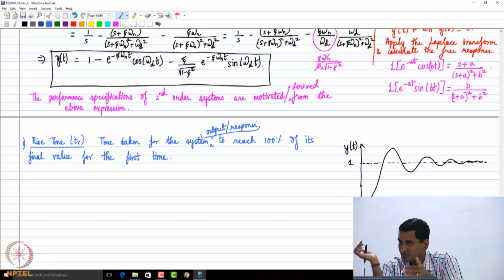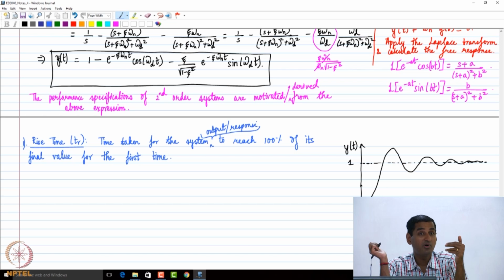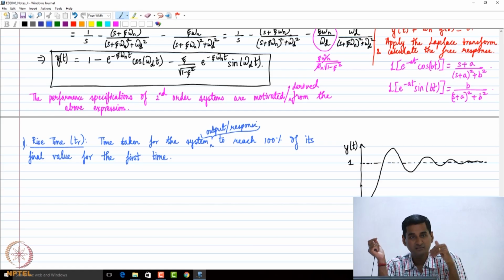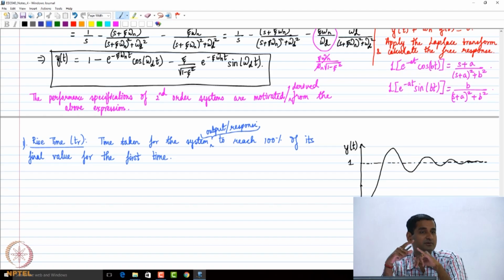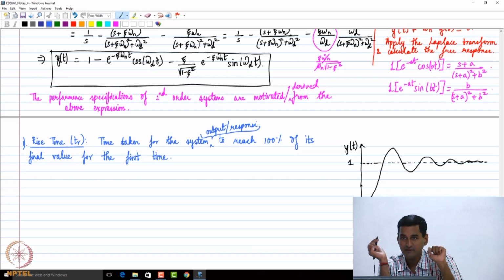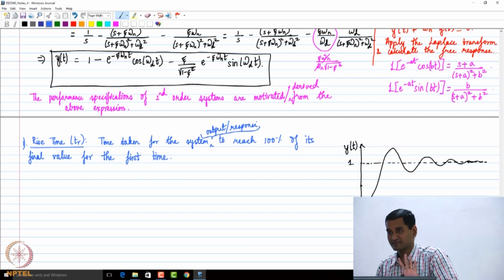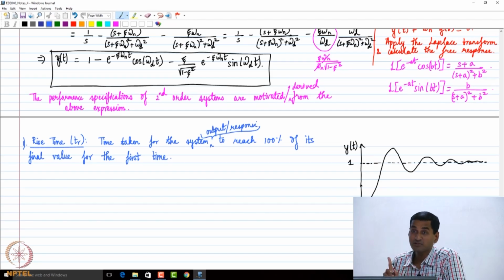That's how these parameters are defined. In the same way, as I told you in the morning, we look at the unit step response of a stable first order system to define the time constant and settling time there. Similarly, for these parameters that we are going to define now, we are looking at the unit step response of a stable underdamped second order system. Please remember that. I am deriving it in flow with the derivation, but I just wanted to explicitly point it out to you.